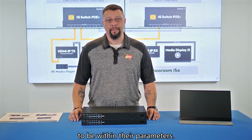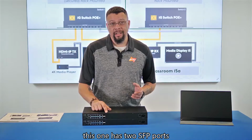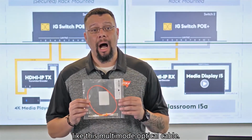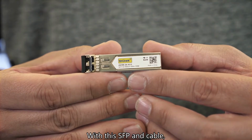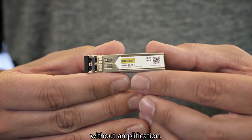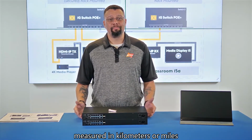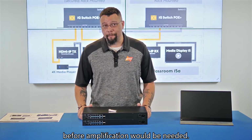be within their parameters. Like many larger switches, this one has two SFP ports that will enable us to use other physical media, like this multi-mode optical cable. With this SFP and cable, our signals can travel up to 550 meters without amplification. Similar SFPs and optical cable can travel distances measured in kilometers or miles before amplification would be needed.